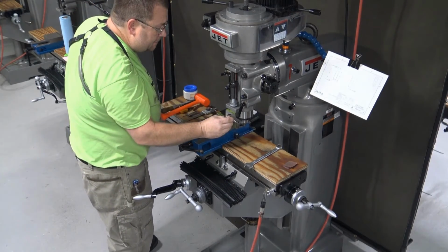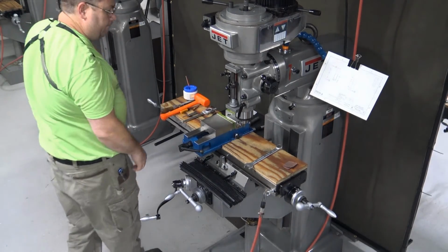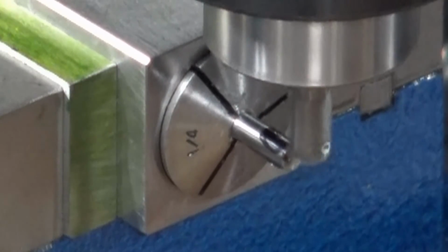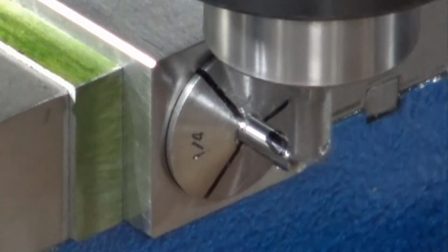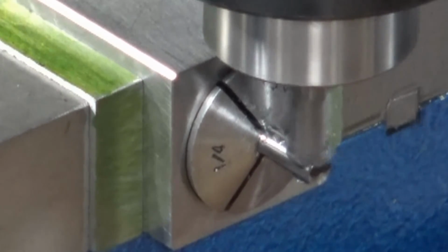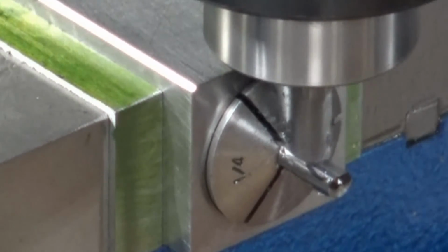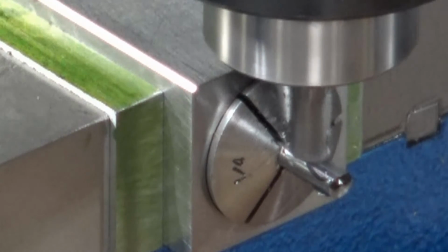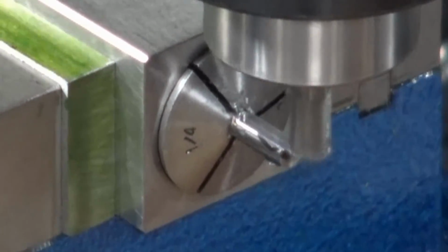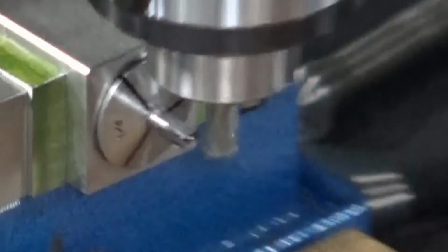So let's go through that process. Let's put cutting oil on it. I've got my zeros referenced. So I'm going to feed up 30 thousandths. I'm going to come in till it just starts touching, and there's my zero. So now I'm going to feed in 600 thousandths. So 600 is 3 turns of my hand wheel. 2, 3 turns. Now normally I'd be on the other side and actually could see myself cutting the material. Because if you get to a point where you're going to run into something, you want to be able to stop, right? So I'm kind of machining blind here, but for your benefit, of course.